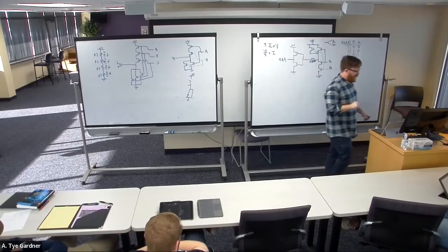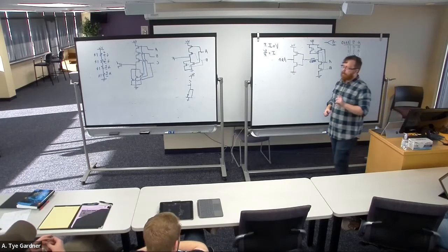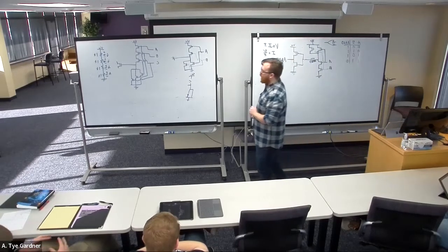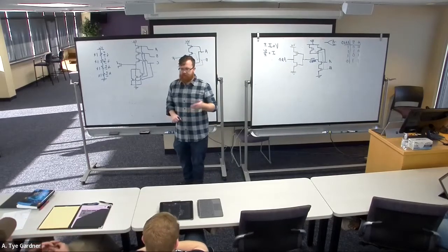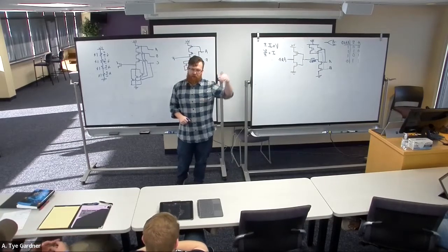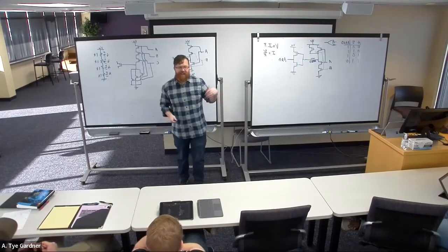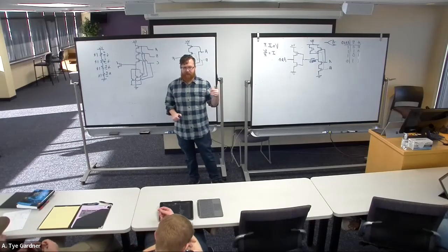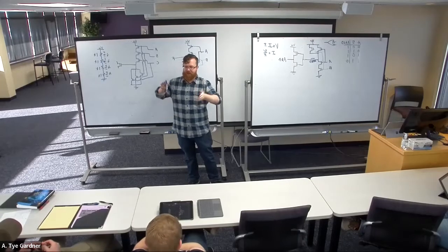Because you have to understand delays eventually. So isn't it going to be slower if you add more components to it though? Like when instead of just using a 4-input AND gate, if you use 3 2s, wouldn't that be slower? Yes, there's more delay the more layers of logic you have. But there's the trade-off that they're actually smaller devices when you do that, so then it goes faster. And I actually don't know where the analysis falls out. It probably depends on process to process. It might literally change from company to company where that trade-off falls.